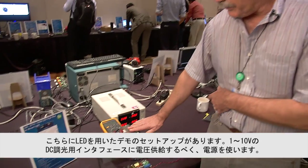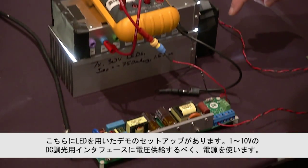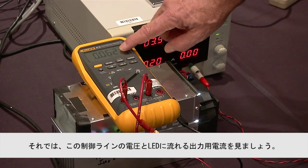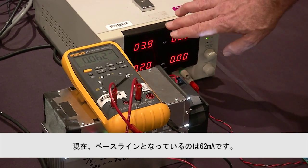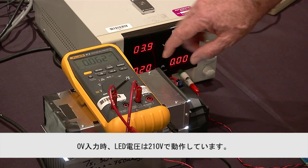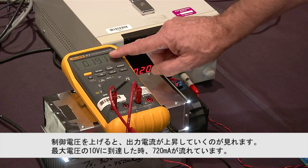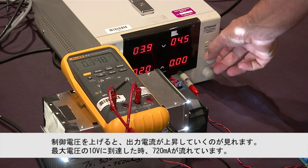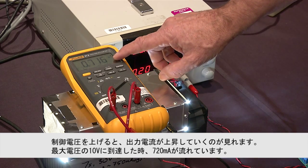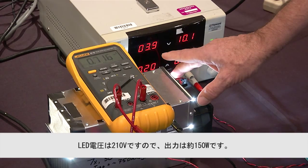I've got a setup here with an LED load, and we're using this power supply to provide the 1 to 10 volt interface for dimming. So we're going to watch the voltage on this control line and the output current that's going to the LED. Right now it's been set up with a baseline of about 62 milliamps, and we're running at about 210 volts on the LEDs with 0 volts in. As we increase the control voltage, we can see that the output current is in fact increasing, and when we reach a maximum of about 10 volts, we're running at about 720 milliamps. And again, this is with a 210 volt load, so we're outputting at about 150 watts.